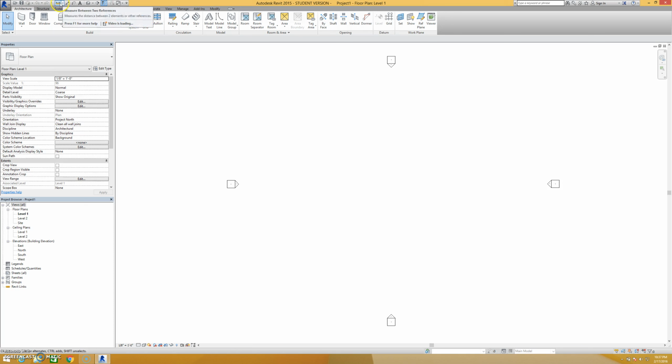The ones that are really valuable, in my opinion, when I use this program are obviously you can use Control-S for save, but you can also click Save here. If you're working in a work sharing program, the Synchronize and Modify Settings button is fantastic. You have the ability to undo multiple steps here, so that's kind of nice if you don't want to hit Control-Z a million times. And the things that I think are really valuable are this button called Thin Lines, which toggles whether or not the line weights appear on your screen, and then this tile window button where you can go through and see all your open windows.